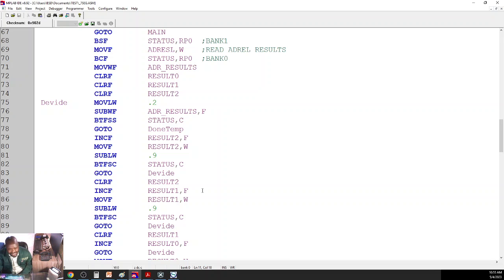If the units are less than 16, switch on the heater. If the units are greater than 16 and the tens is equal to 1, switch off the heater. For the fan, I need to go and check the tens. Are they greater than 2? If they are greater than 2, then automatically switch on the fan, because temperature will be greater than 27 if the tens are greater than 2.